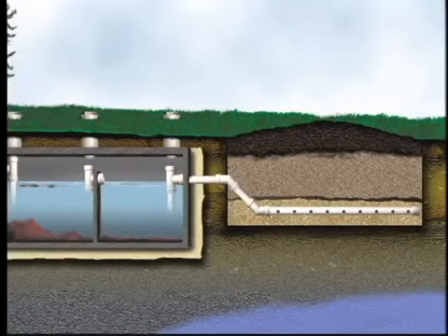The components are available in a variety of sizes and have connectors to allow construction of trenches to follow the contour of a site. However, you should be aware that maintenance and soil requirements for this system are quite similar to that of the media-filled trenches. This, too, is not a good option for soils with high clay content.